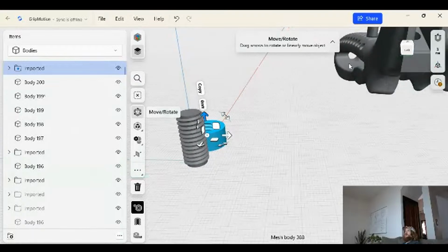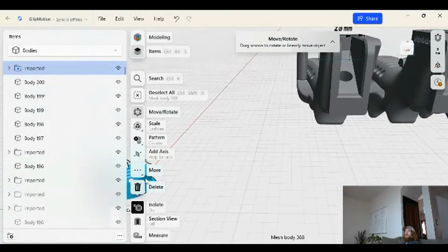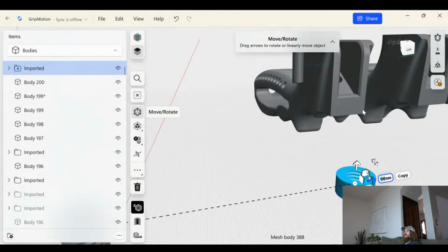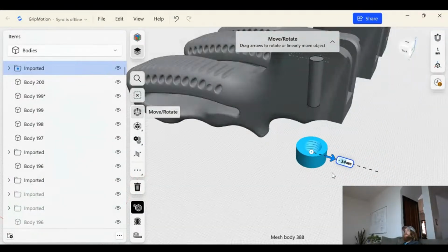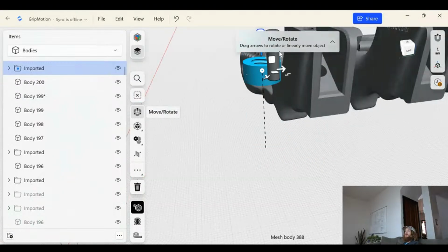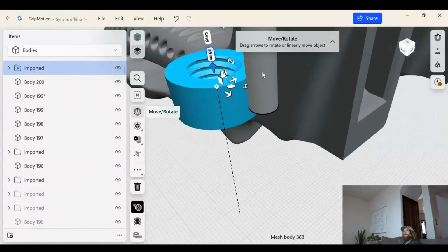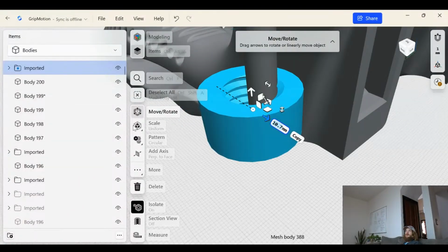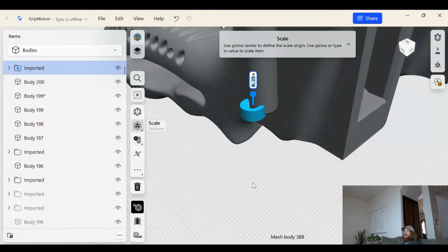Okay, so I'll have something around. It's been a while since I've done it on the free versions. On the professional version, you can just export at the high quality. You'll take an STL that you got online, an imported file that is already of the highest quality, bring it in, go down here to scale, and we're going to scale it way down.